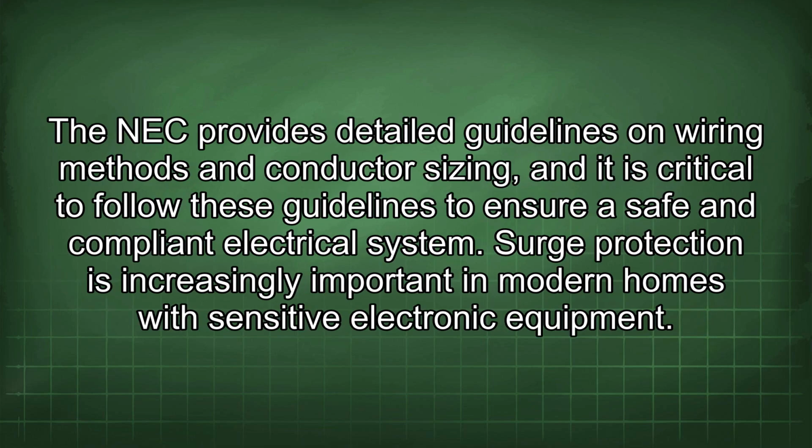The NEC provides detailed guidelines on wiring methods and conductor sizing, and it is critical to follow these guidelines to ensure a safe and compliant electrical system. Surge protection is increasingly important in modern homes with sensitive electronic equipment.